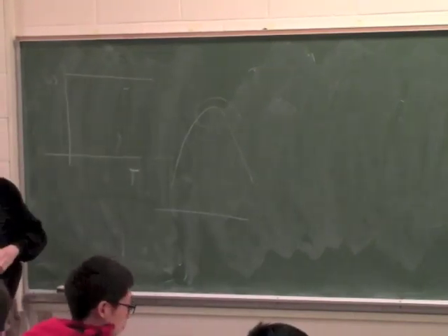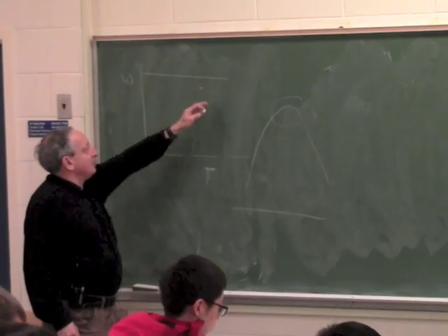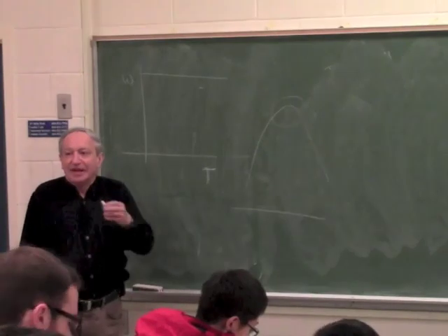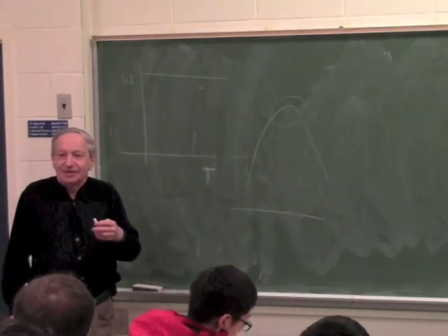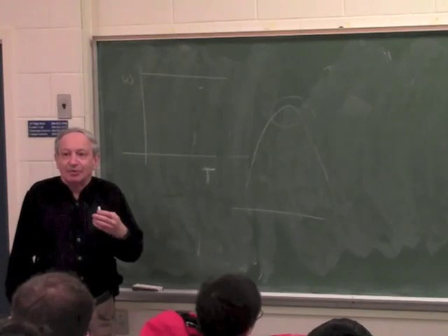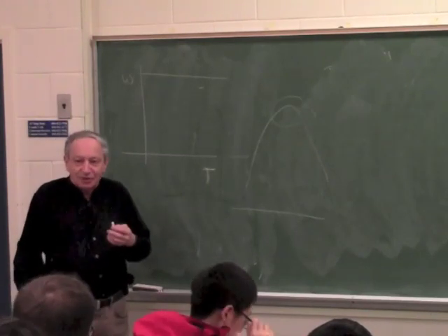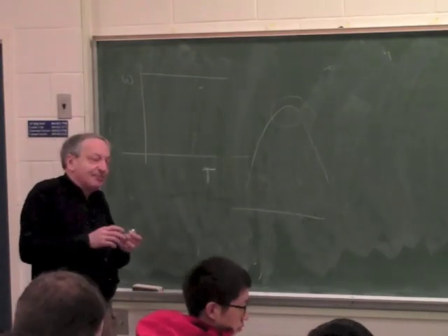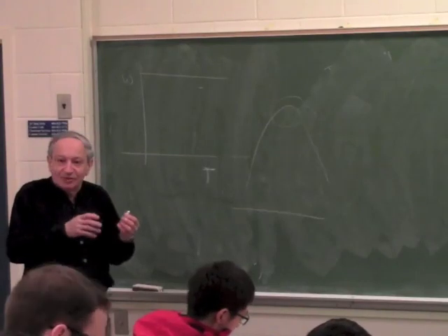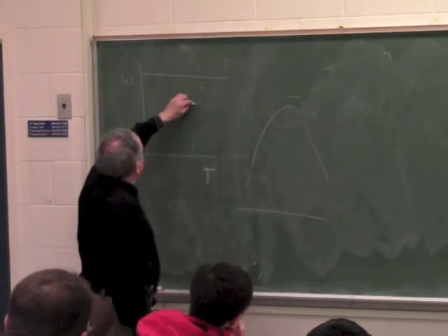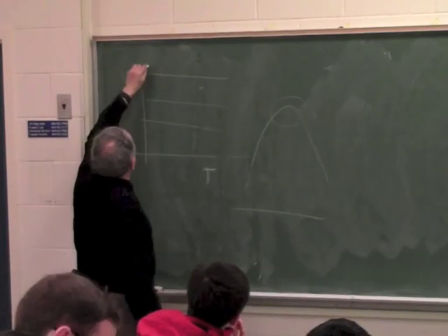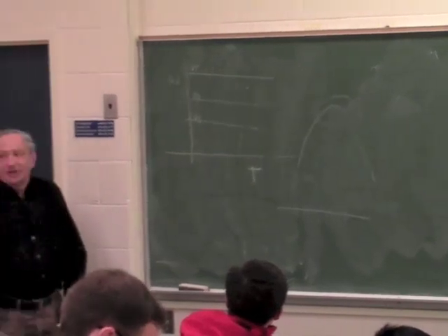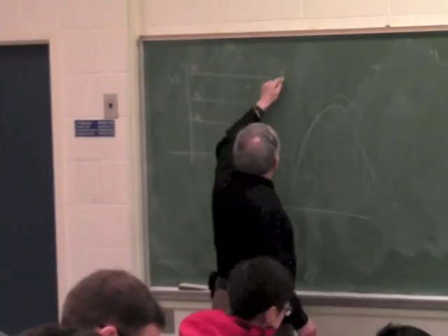They were PMDC type motors, where the speed dropped a little bit when the torque went up. And the reason the speed dropped, I'm reminding you, is because of the IR drop. The more torque, the more current, the more IR drops. So the actual voltage the armature saw was dropping, so the speed to match the EMF also dropped. As you recall, there was a family of curves, V1, V2, V3. As you lower the voltage, the curves drop, and this was PMDC.